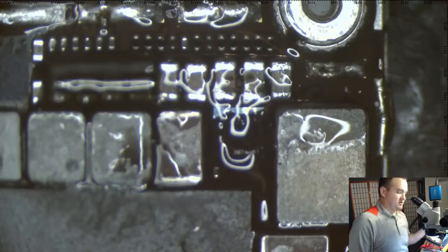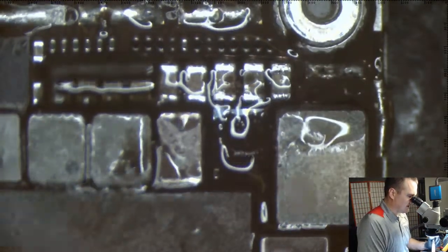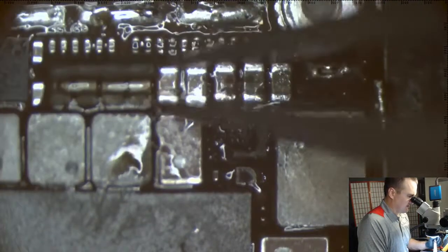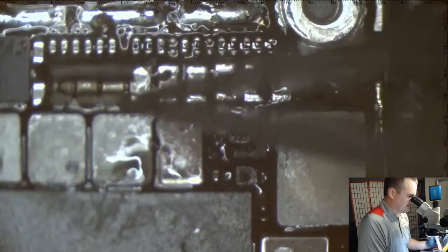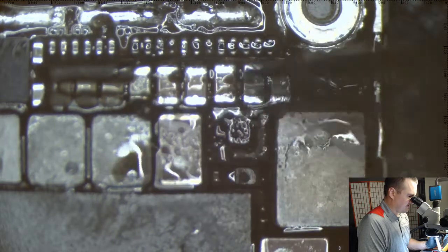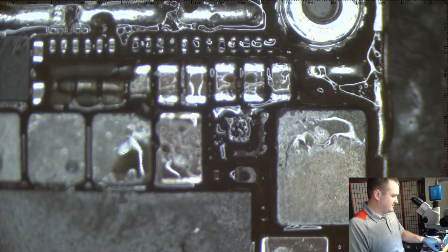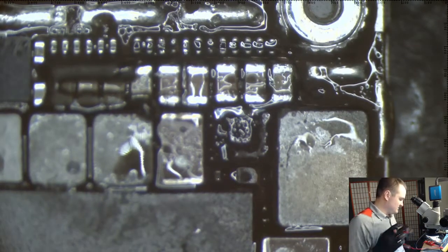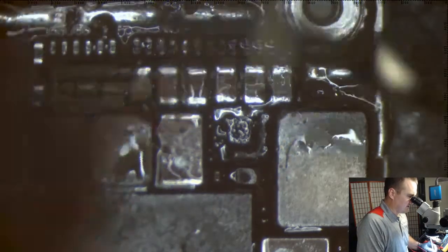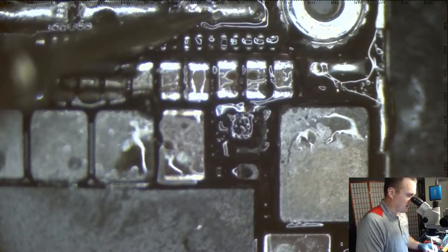Now, if we get it right on the first try, I'll probably just leave that cap off and not replace it. I've done enough of these to have seen there are really no ramifications to losing one capacitor. Now, if you take all three off, you might get some flicker that doesn't go away. They're smoothing caps, so they're taking that oscillating power input and they're just smoothing it out. It's like a battery. It's got one foot on ground.